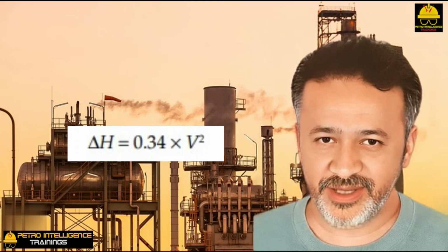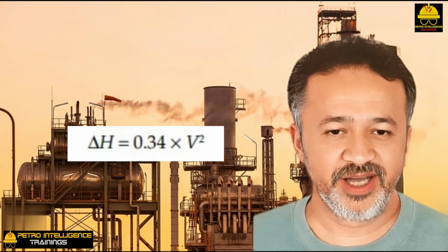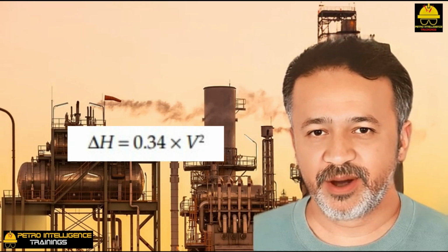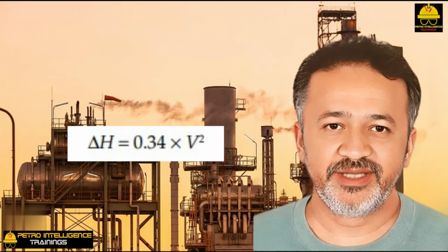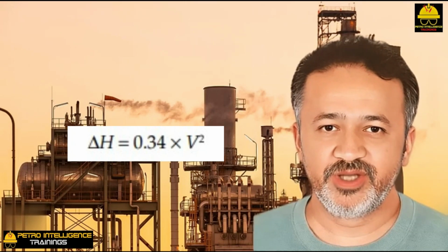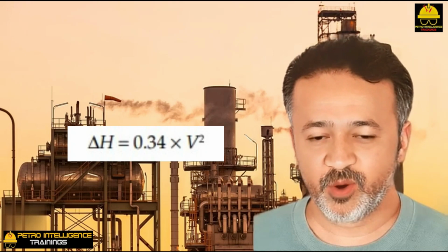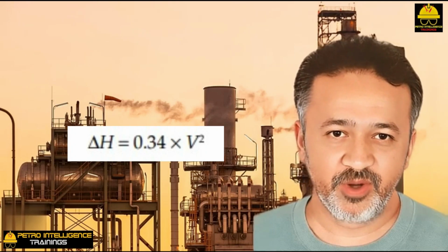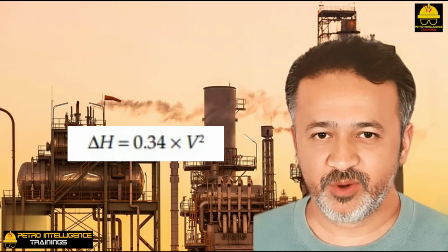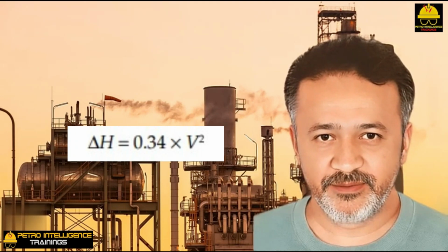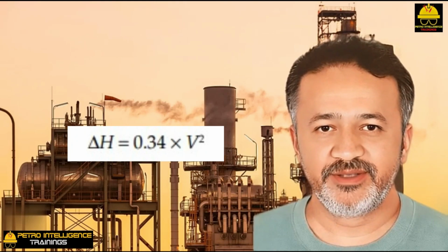I like to prove it myself, prove it by experimentation. What I'm doing is running water into the bathtub at a measured rate. I wait for the water to drain out until an equilibrium height is established. I have to get the height, delta H, high enough to suppress vortexing. Then, using the diameter of the drain, I calculate the velocity, V, of the water flowing out the drain. I can then calculate the coefficient, 0.34.